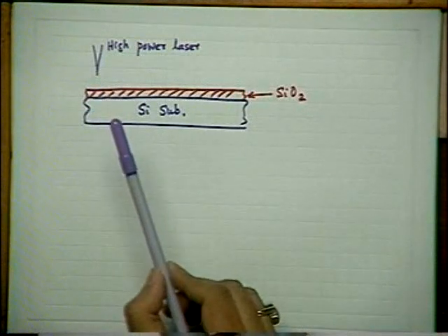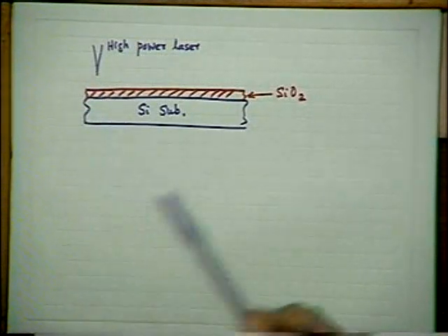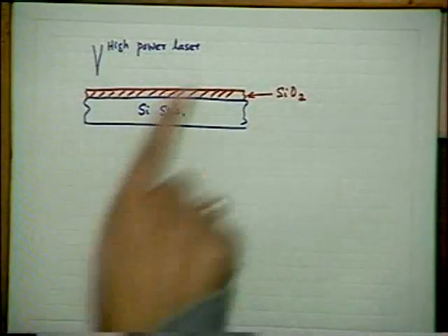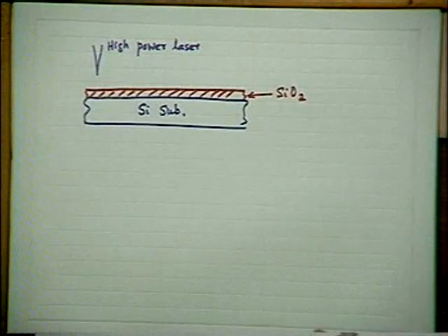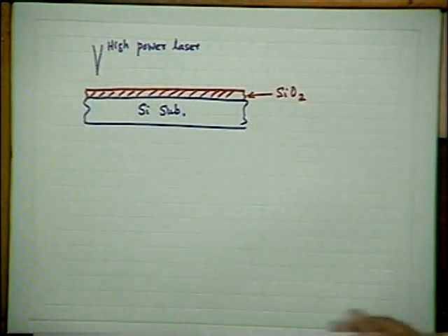High power pulse lasers is not a continuous laser, so that average heating is less. Heat is a local heating, both in time and space. As the high power laser sweeps across two-dimensionally, of course, you have to make a two-dimensional raster scanning. Then what will happen? This molten silicon propagates along the surface. And a technique called zone refining and melting cum resolidification takes place, which ultimately produces a crystalline silicon film on the top.